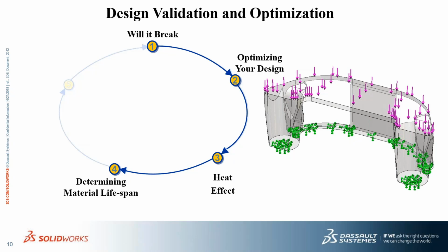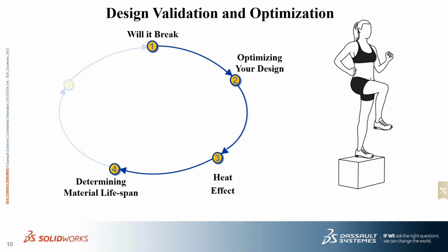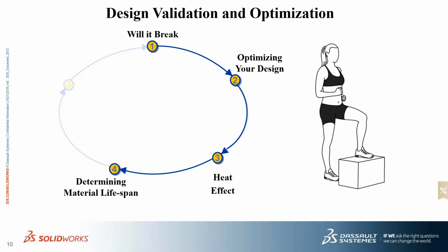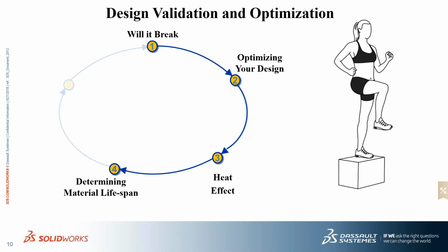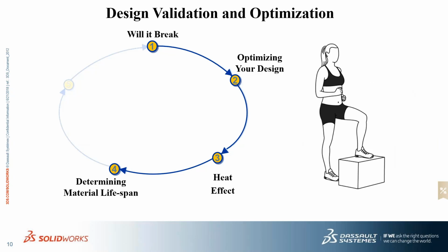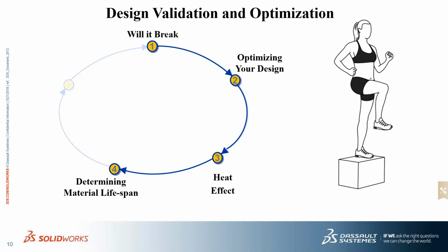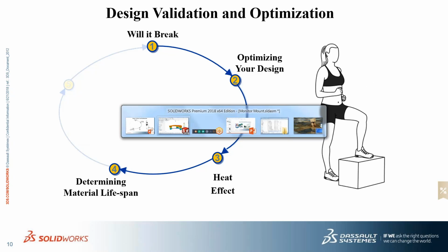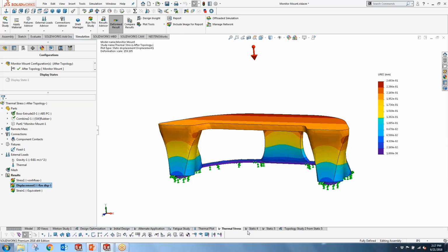So the scenario here is, we know that our monitor mount can hold up the monitor, but maybe a colleague of ours, or ourselves, we see this and we're like, this kind of looks like a step stool. And we want to see, maybe we can print these and save money, but someone's going to be walking on this thing quite a bit, up and down, cyclical loading, and we need to know what the safety of this is and if it can even handle that type of loading. And so we move into a fatigue study.